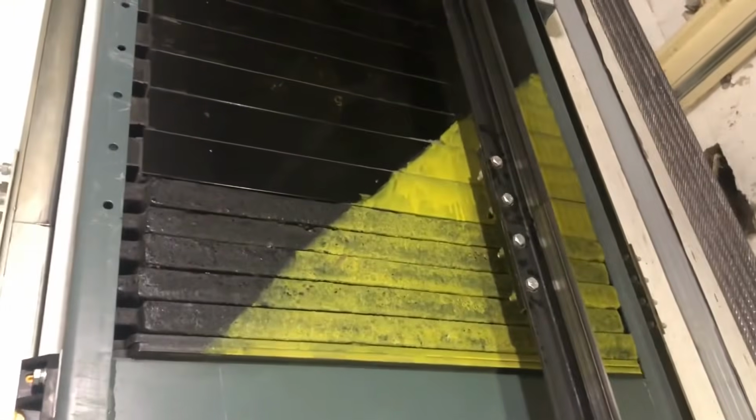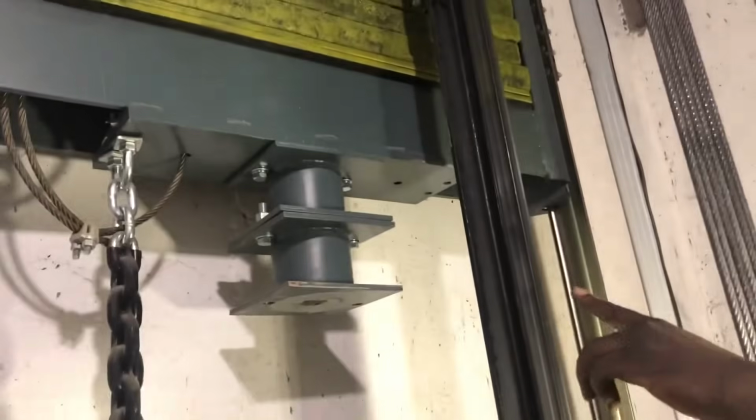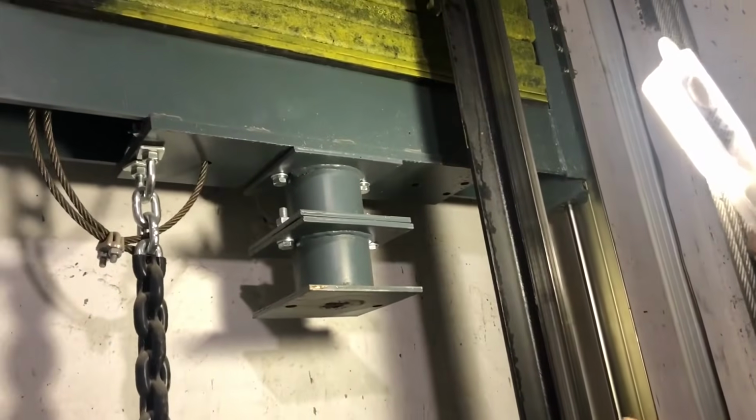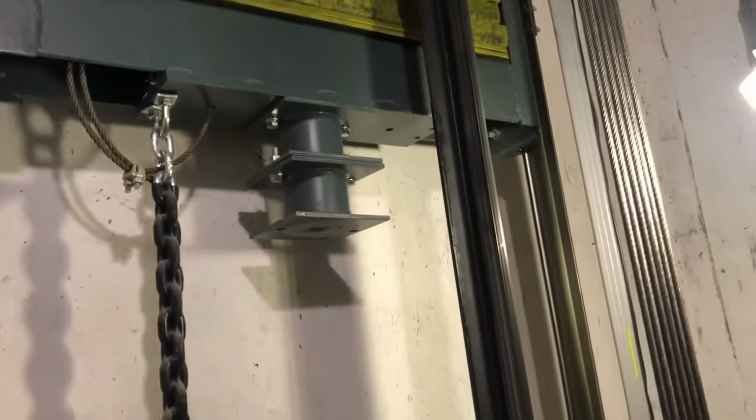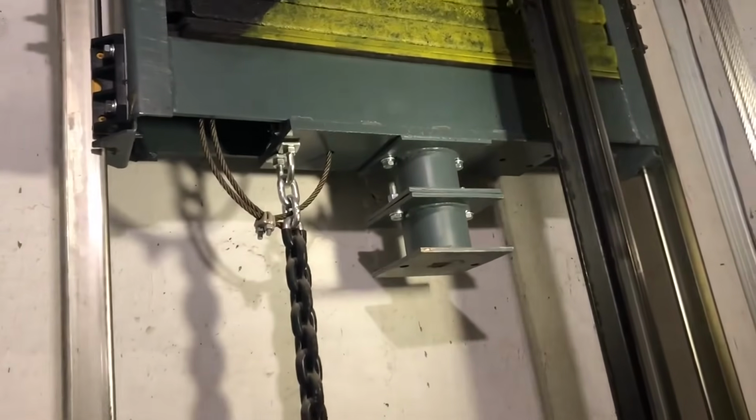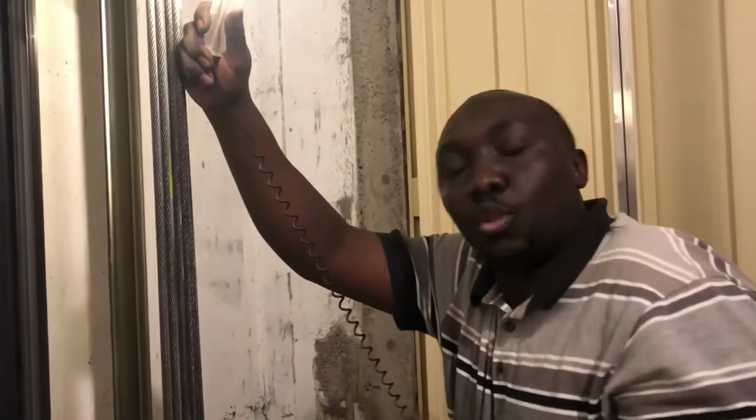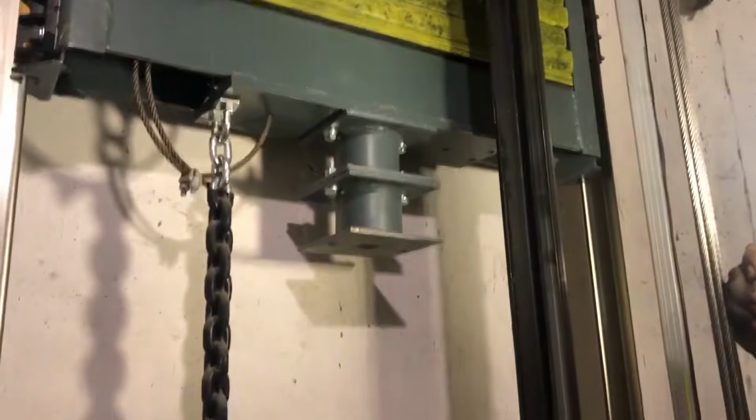Okay. Let us go down. On the counterweight, you can see the chain, and you can see something that looks like a stand. The stand is normally for when the lift is running and maybe it overshoots the floor. The counterweight strikes the buffer. The buffer is the final limit switch to stop the elevator. Very, very sensitive and important part of the elevator. This is the work of that. The chain is just to compensate the weight.